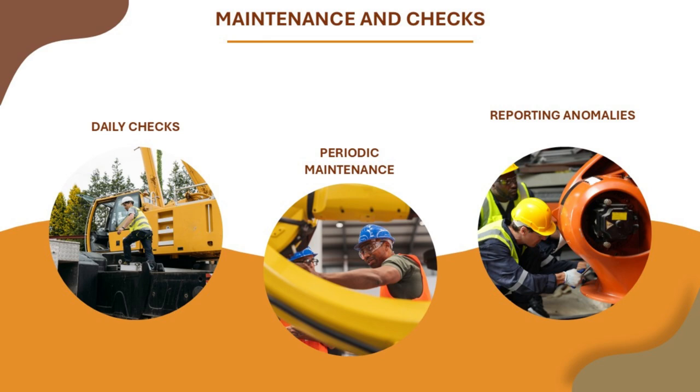Periodic maintenance. Carry out the maintenance operations indicated by the manufacturer. Record all inspection and maintenance operations in the crane logbook. Reporting anomalies. Any malfunction or damage must be reported immediately to the person in charge. The crane must be taken out of service until repaired.